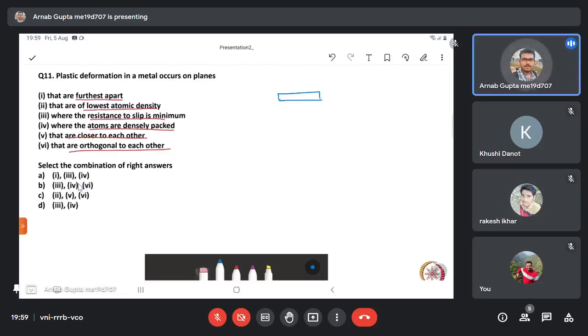Okay. So see, most of the metallurgy people will be doing this. Say you have a material, you want to see the grain distribution, how the grains are distributed, what are the grain size, all these things. So they will polish it up to a mirror finish. This involves multiple levels of polishing using polishing papers, and after that, diamond suspension, diamond paste, or some colloidal suspension. So you will get a mirror finish. After that, you do etching. Different commercial etchants are available.